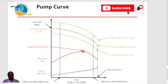So all centrifugal pumps can handle a range of different impeller sizes, ranging from minimum impeller diameter to maximum impeller diameter. This must have been specified by the OEMs on the pump curve. As per process requirement, the impeller trim is chosen so that the pump can meet the rated point or the duty point.